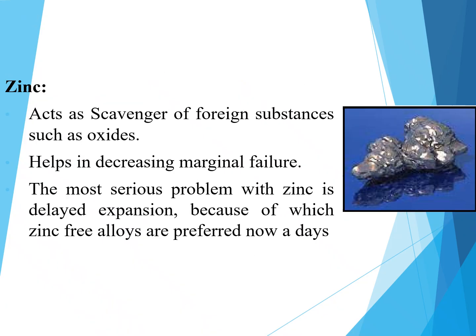Zinc. It acts as a scavenger of foreign substances such as oxides. It also helps in decreasing the marginal failure. The most serious problem with zinc is delayed expansion, because of which zinc-free alloys are preferred nowadays.